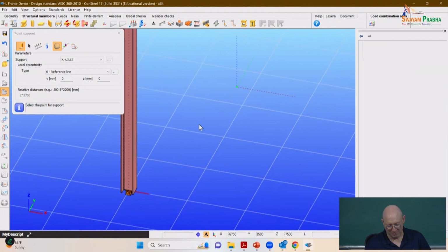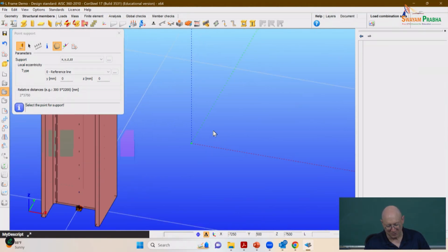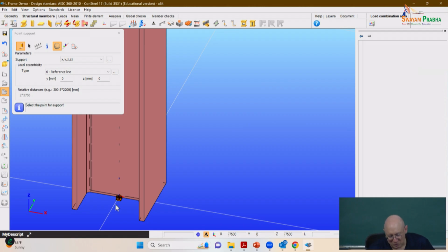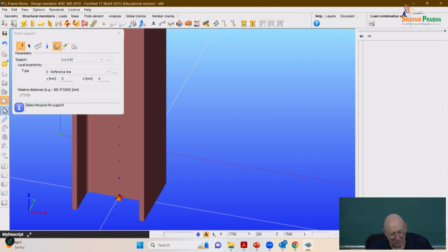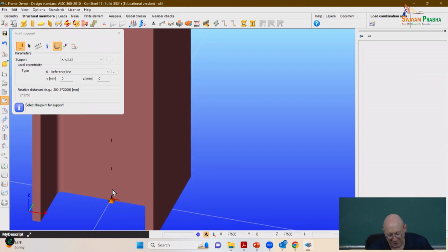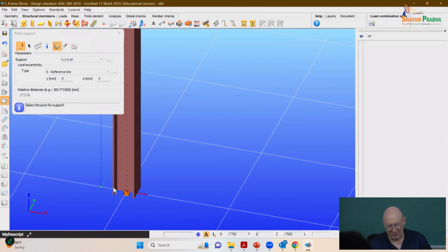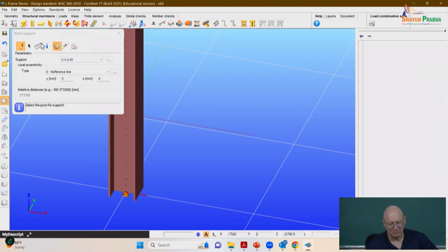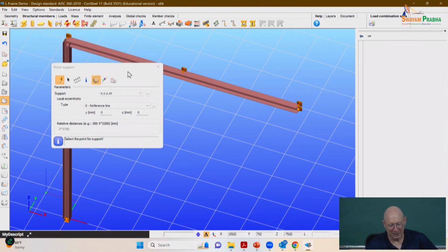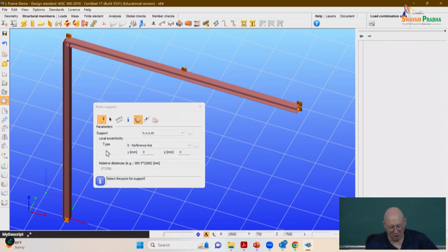So if we zoom up on that, we can see a graphic that looks a bit like a pin. Okay. All right, so I'll go back to perspective view. And now we need several other supports. This column is going to need bracing basically at 1/4 of its height out of plane on each of the flanges.